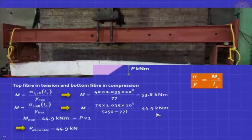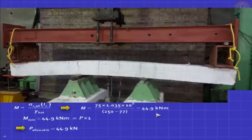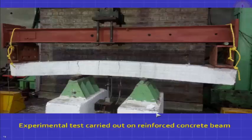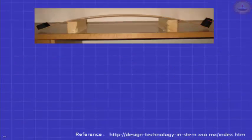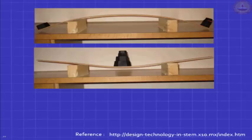We actually do tests like this in our laboratory. This is a test done in the structural engineering lab at IIT Madras. This is a reinforced concrete beam. You will see that the top fibers are subjected to tension. Concrete is weak in tension, so it kind of cracks here. There are two concentrated loads being applied here, P and P, and you can measure strains and curvature and all that. So these are very simple tests to demonstrate. You'll find that here you have constant radius of curvature, but in these regions you don't. And there are diagrams available like this.